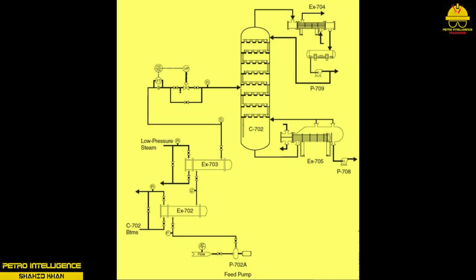Distillation column. The basic components of the distillation process include the column, the preheaters, pumps, the condenser and drum, and the reboiler. A 10 psi nitrogen blanket is kept on the unit while the system is down. The central piece of equipment in distillation is the column, as shown in the picture.